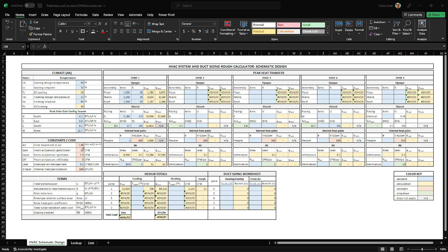Okay, so what's next? We've got a cooling load and a heating load. Now we need to figure out how many CFM we require for each of those, and then pick the one that's largest to design our ducts with. Hopefully that makes sense. By the way, everything we're doing is what you did when you went to the book and looked up the rule of thumb, tons of cooling. That was just a simplification of all this stuff. We're just dialing in to get more detail and allow us to adjust things in a more nuanced way if we want to.